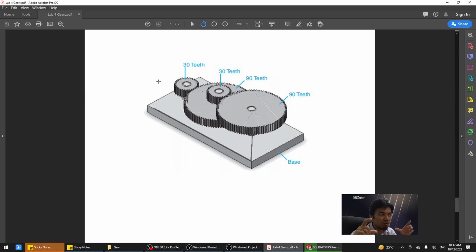For this one you need to draw a base first, then the gears come later. So for the holes where you put the shafts, you must first measure the location of those holes. How to measure that location, you have learned in the lesson where I taught how to calculate the reverted gear train. You learned how to find the center of that shaft. That is where the calculation is used, to find where this point is.